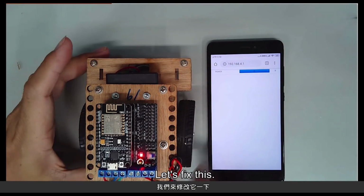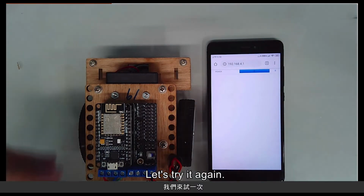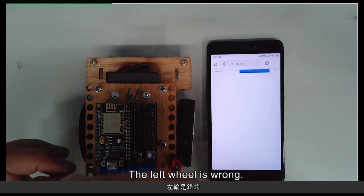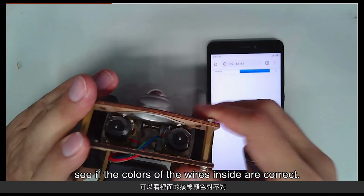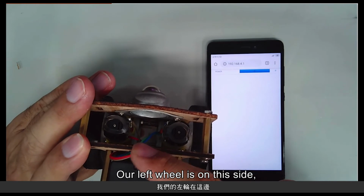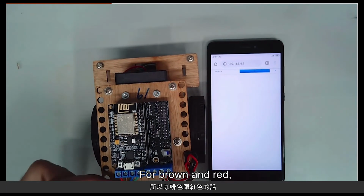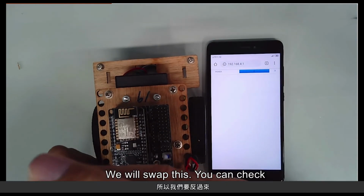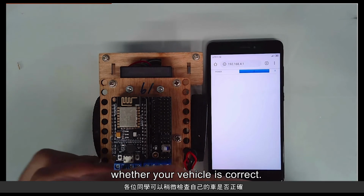Let's fix this. Make sure the power is cut off when swapping the wires. Let's try it again. The left wheel is wrong. Check the left wheel to see if the colors of the wires inside are correct. Our left wheel is on this side, the wires are brown and red. Brown and red is the left wheel and motor A, this is correct. We'll swap this, and you can check whether your vehicle is correct.